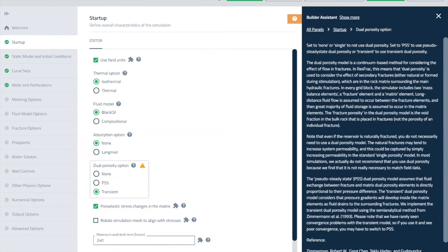Yeah, and this is Joe. Back in the early 90s when we were building our first finite difference model to handle a shale and put in dual porosity, at the time, coal bed methane was using a lot of pseudo steady state options. And because the cleats are so small, a quarter inch or maybe a half inch at most, you get into pseudo steady state pretty quickly.